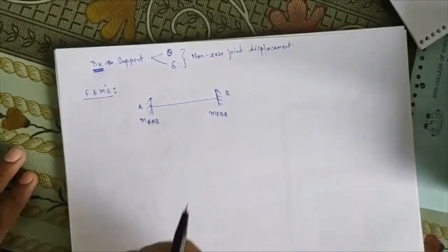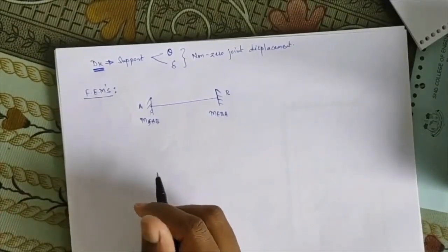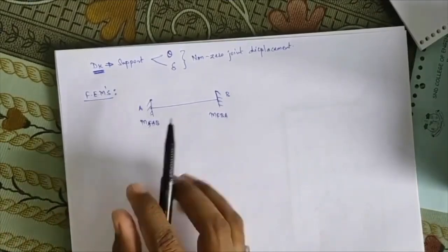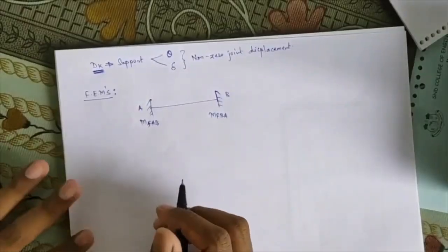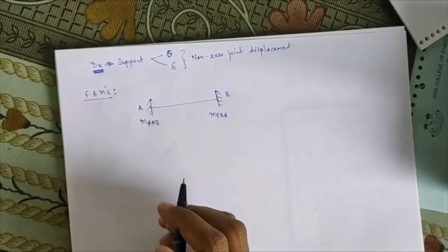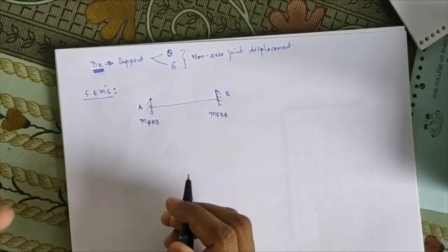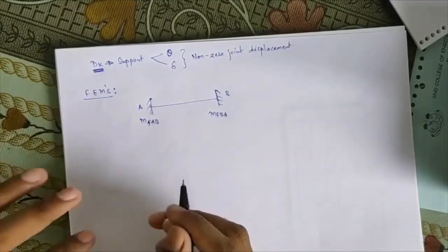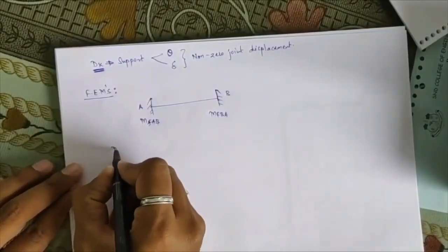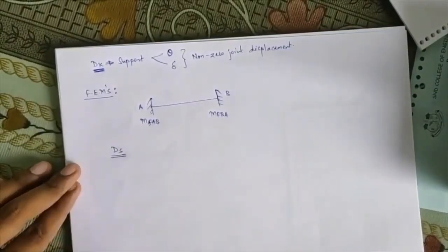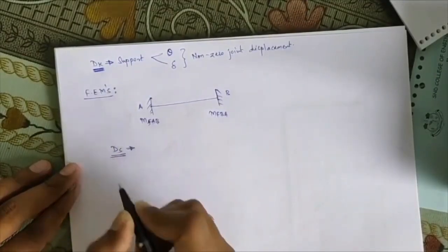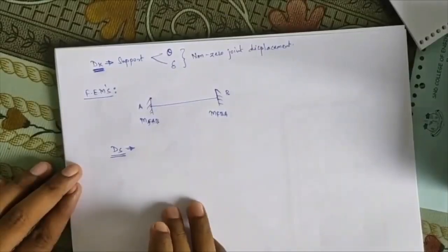Okay. So from here onwards we'll start with your unit number 1, that is the slope deflection method. In this method, basically you have to deal with the transverse displacement at the ends and the transverse slope at the ends of any member, which is related to the basic unknowns. Mostly in the slope deflection method, we deal with DS number of unknowns, that is degree of static indeterminacy. We will need to calculate it in the very first step of every numerical.